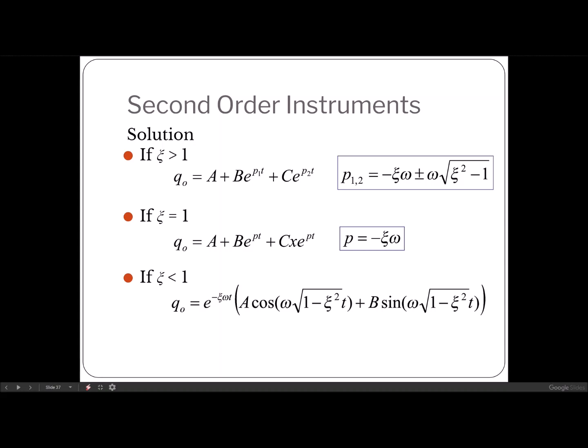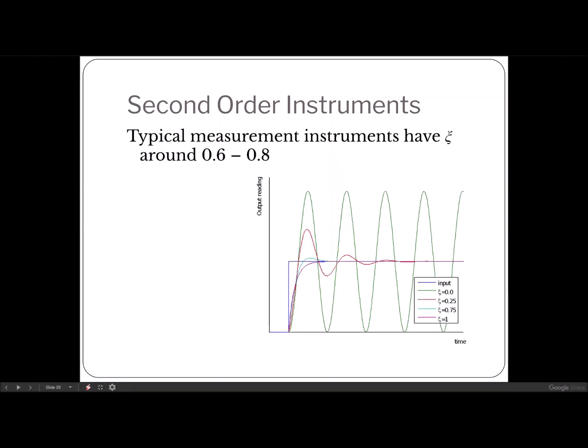when it is talking about second order systems, and then you will refresh your memory about this. Okay, but this second order system applies also to some types of measurement devices. A typical second order measurement device will have eta or damping ratio between 0.6 and 0.8 for a certain reason. Why? Because when your damping ratio is in this range, the rise time will be reasonably fast.